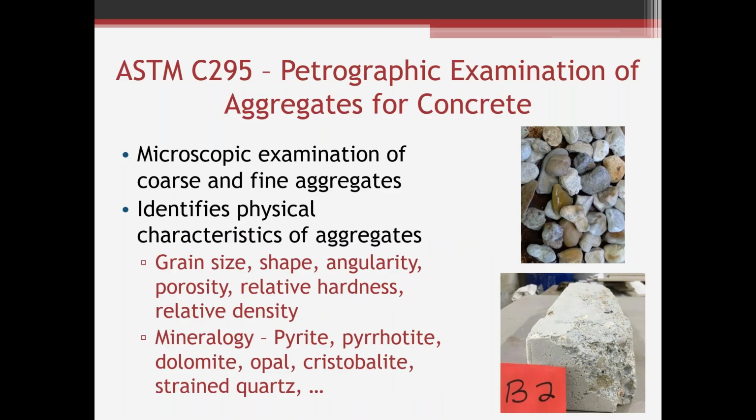So we'll talk a little bit about ASTM C295, petrographic examination of aggregates. This is a microscopic examination, of course, in fine aggregates. We're identifying physical characteristics, and remember, a lot of times these physical characteristics impact the quality or the performance of the aggregates.